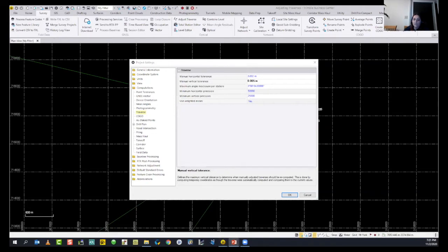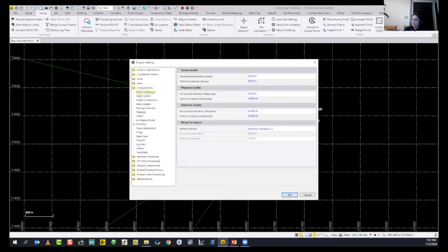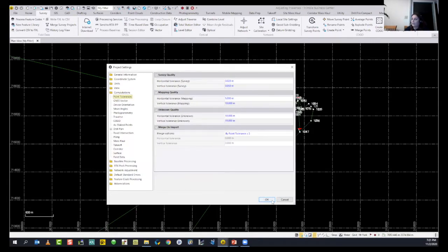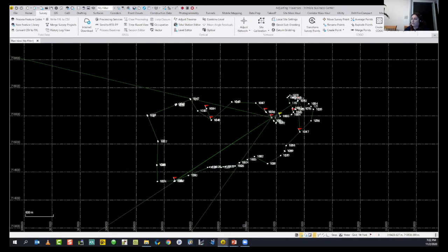What you can also change is the point tolerances. Right now we have some data. Let me show you the data first. Let's say OK. As soon as you click OK on the project settings, the change will be applied to your project. If TBC requires a computation, you will probably see a red dot on your status bar. You can also compute your project with F4 or the Compute Project icon on the Quick Access toolbar. Then all of your changes will be applied to the project.